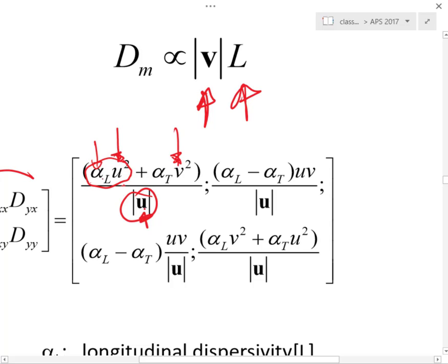That's the longitudinal dispersivity that has units of length, and then this thing here, that's this u. This is the component of the velocity in the x direction divided by the average velocity. So this has got units of length. This has got units of velocity, or length per time, when we take that squared and divide it by that thing. Okay?